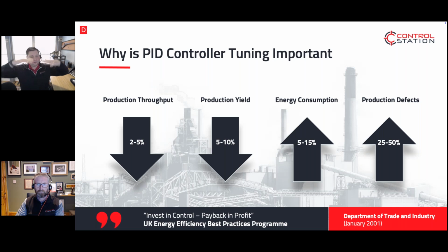If you can stabilize control, all of that variability could be considered wasted energy, and you can move those set points a degree or 2 degrees lower based off that variability improvement, and you can improve your energy consumption by 1, 2%, 3% pretty easily. I've done projects where we looked at all the steam users and all the chilled water users, looked at all of their variability, tuned them, and then moved the set point up or down, depending on if it's steam or glycol, to be able to recover some of that energy a little bit better.